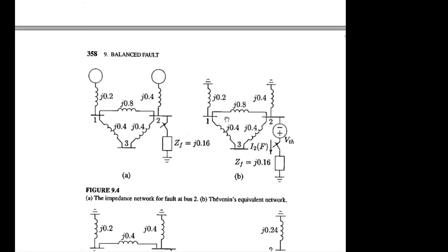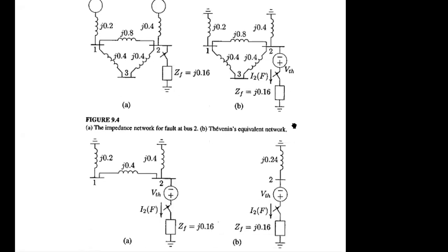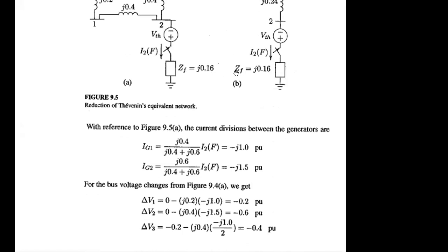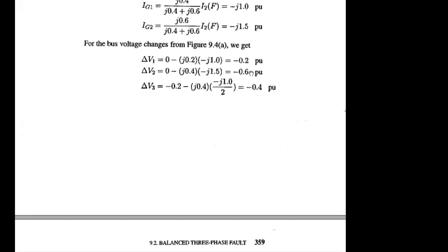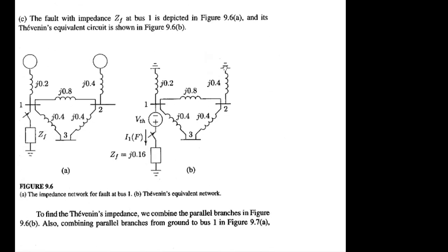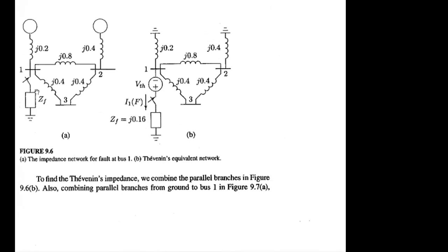So you have to generate the equivalent impedance considering the bus 2 scenario. So we can find Z22 now. The equivalent impedance for bus 2 will be Z22, and we already have ZF there. The similar principle is applicable to determine Z1 as well. If it is Z1, that means bus 1 is attached, and in that case you have to find Z11.